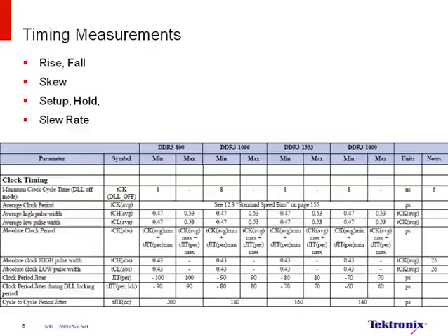Some of you may not be aware that rise and fall are jitter measurements. However, if you think about it, variations in rise and fall timing directly affect the timing of the edges and hence affect the jitter. Again, on these measurements you see on these slides, statistics are really important to be able to perform a rigorous analysis of these measurements. Similarly, slew rate is related to rise and fall times. The difference is that rise and fall times do not change with different amplitudes, but slew rates will change with the amplitude you're measuring over.